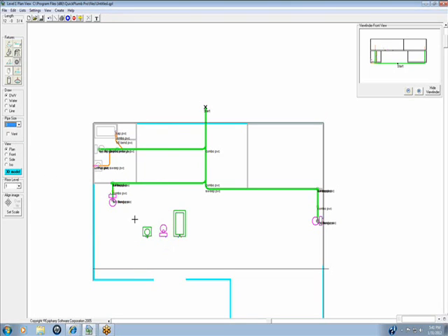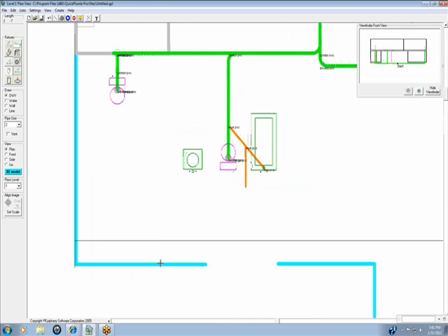We could connect a 3-inch, and then connect our tub, and then our lavatory could serve as a wet vent for the tub and the water closet. Oh. Strictly legal here in North Carolina. That's a lot faster, I'll tell you.